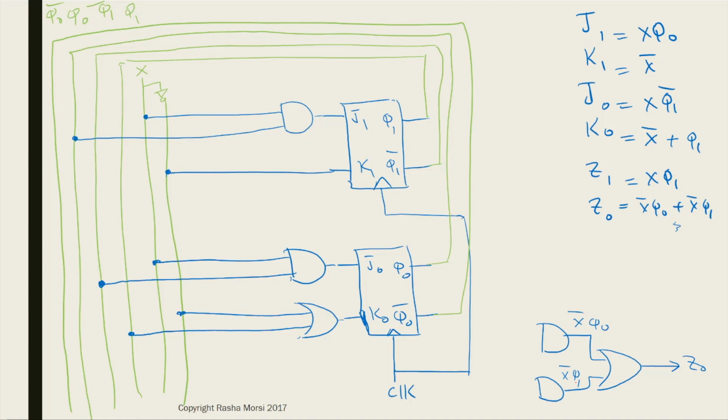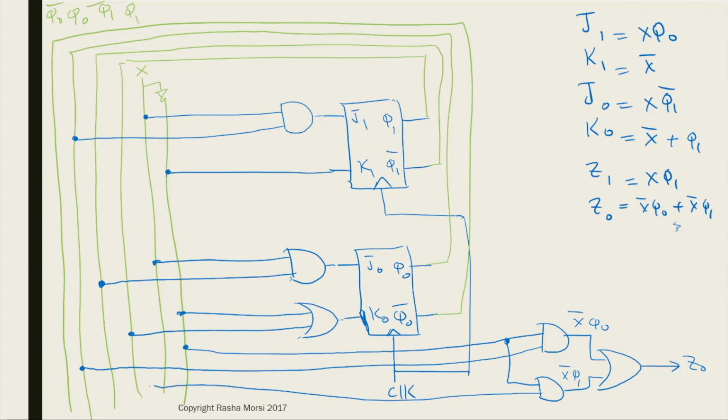So we need to draw these lines, and unfortunately I don't have the right space over here on the circuit. You really need more space when you're drawing these things, so we're just going to take a line straight from there for X bar. And since it's going to both gates, we're just going to connect them together. And then Q0 goes all the way to Q0 and connects with it. And Q1 goes all the way to Q1 and connects to it. And I apologize for the mess on this circuit right now. But when you have a larger piece of paper, you'd be able to draw this better.